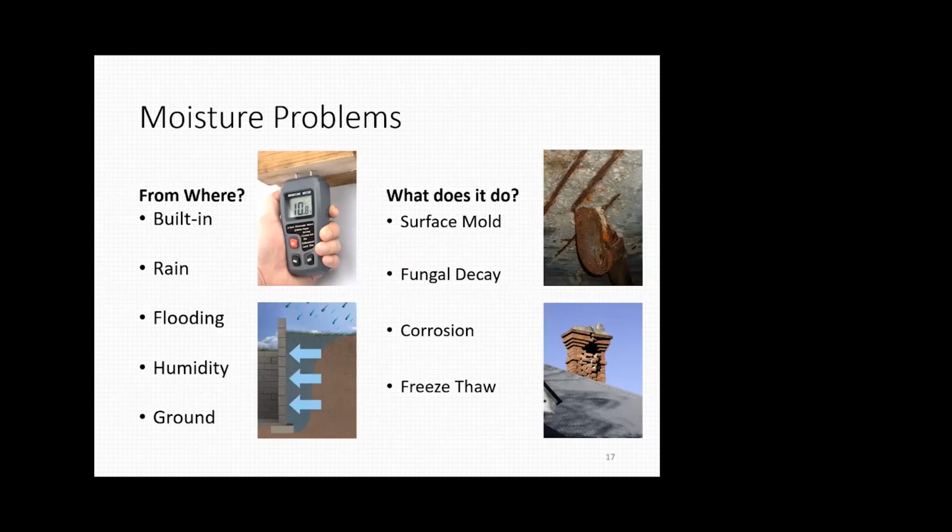Obviously, we have to deal with rain. We spend a lot of time drawing flashing details and moisture management details in our drawings, and then trying to make sure that stuff is executed properly on a house. Flooding, obviously, is another issue we have to deal with. Humidity, as I said before. And the ground, depending on what kind of soil is on your site and how you build your footer and your foundation wall.